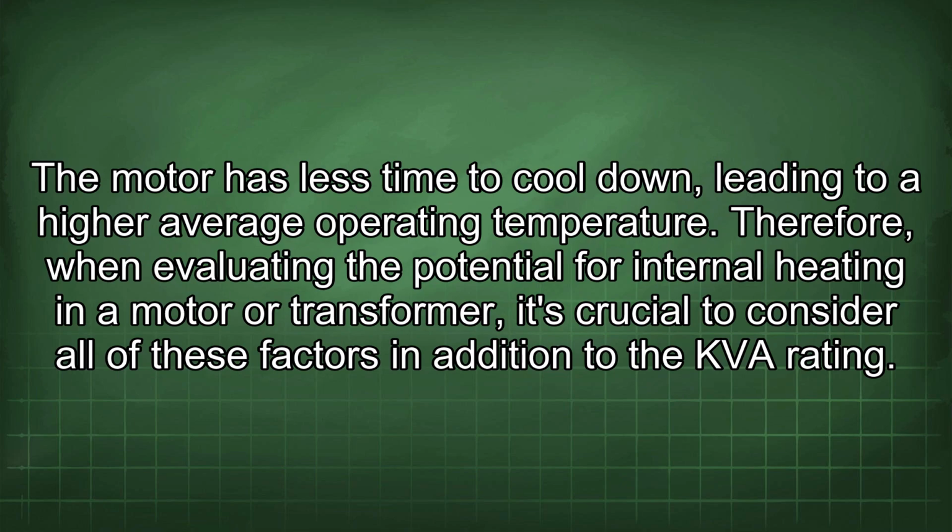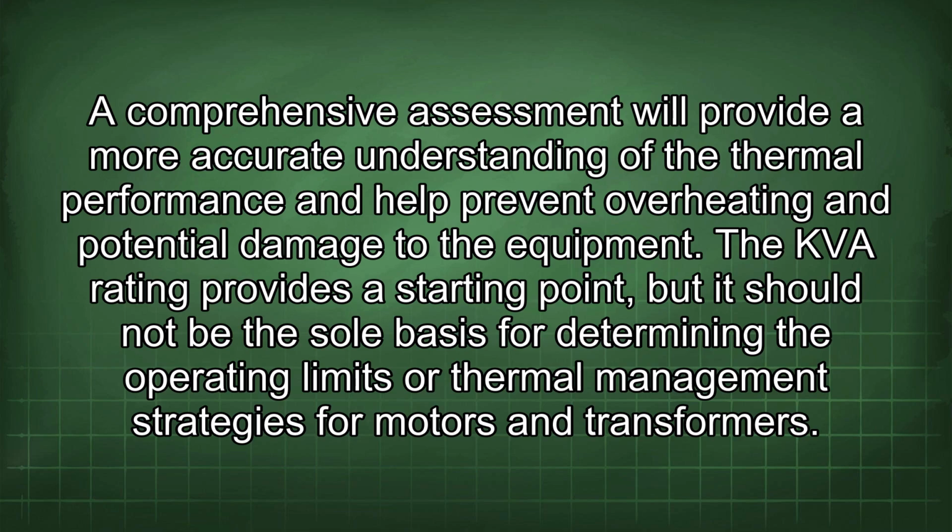The motor has less time to cool down, leading to a higher average operating temperature. Therefore, when evaluating the potential for internal heating in a motor or transformer, it's crucial to consider all of these factors in addition to the KVA rating. A comprehensive assessment will provide a more accurate understanding of the thermal performance and help prevent overheating and potential damage to the equipment. The KVA rating provides a starting point, but it should not be the sole basis for determining the operating limits for thermal management strategies for motors and transformers.